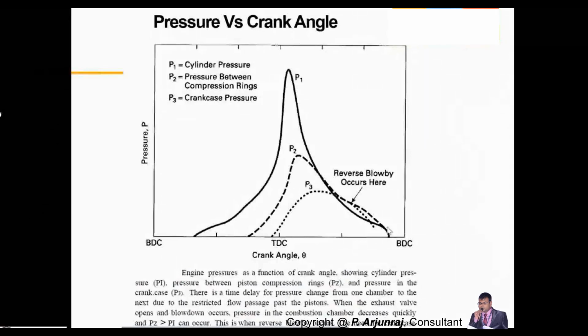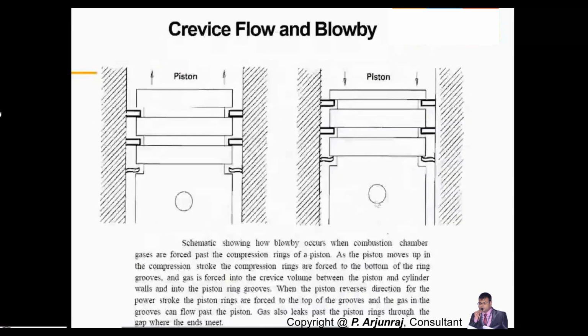Blow-by is nothing but exhaust gas. It has temperature, it has load, it has pressure. So this will also affect your overall system configuration. That's why you need a proper design of the combustion chamber so that you don't get a high amount of blow-by gas.